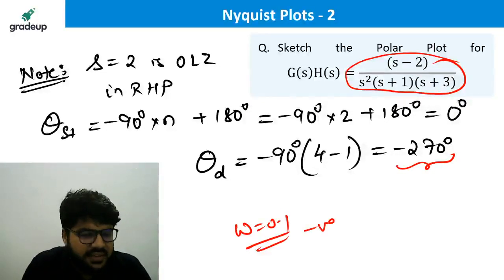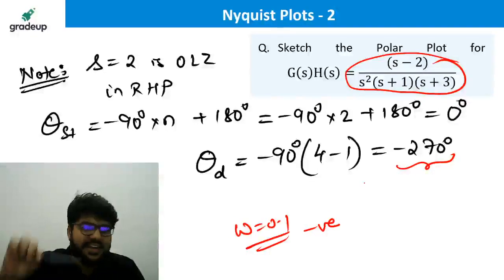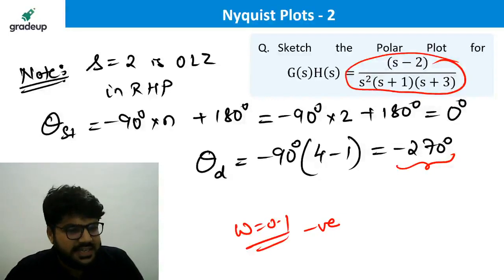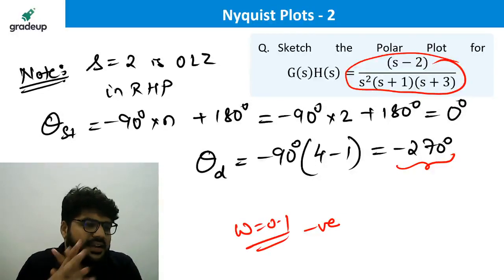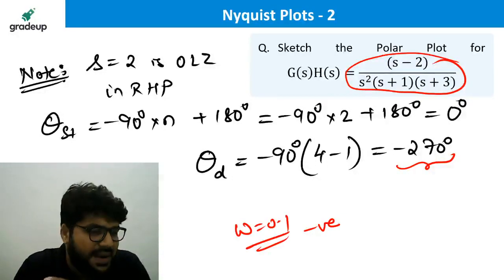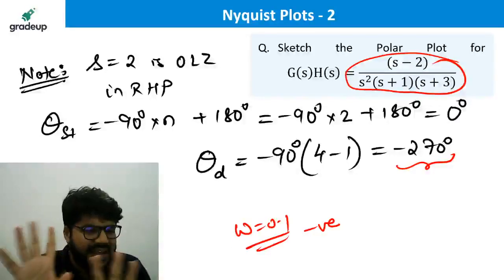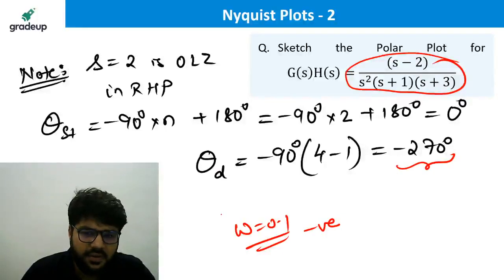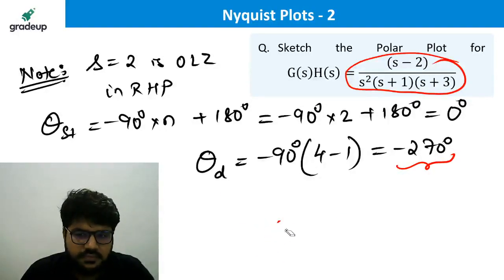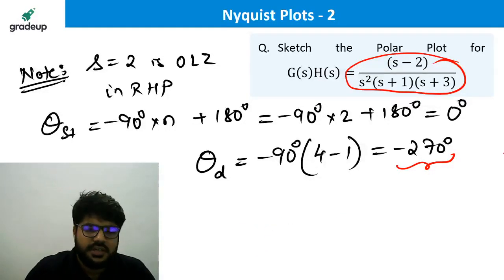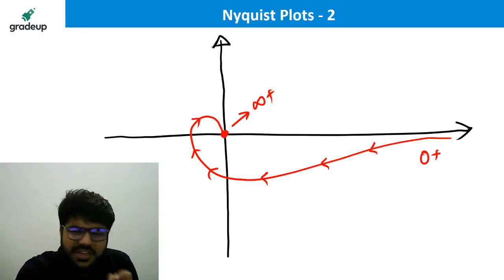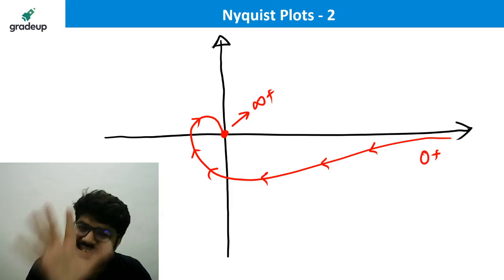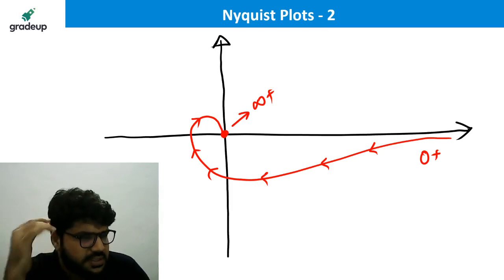Okay, you can check it. I am giving you the hint. It will come up as negative, and negative means again clockwise. So like that you can check, Lasya, Deepa and Zion. Take any small frequency, 0.1, you will get it as negative. So sometimes with the trick, if you have a little confusion, a small calculation is sufficient to eliminate the doubt. If it is an MCQ question, you can use this.